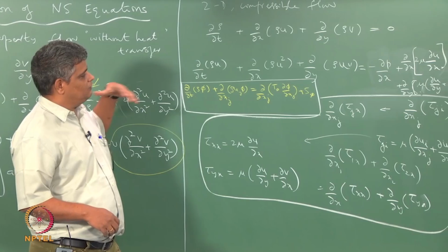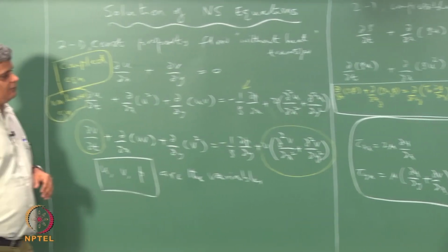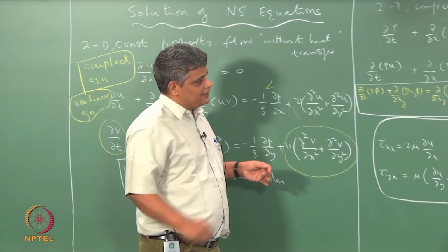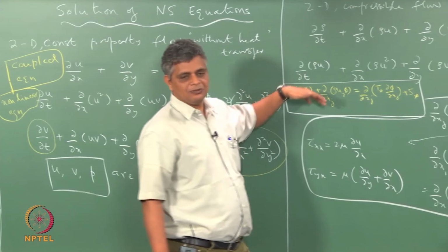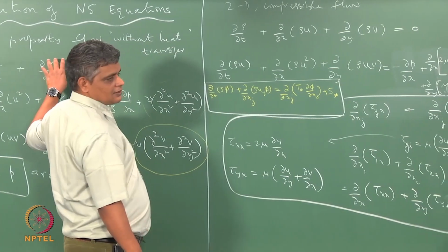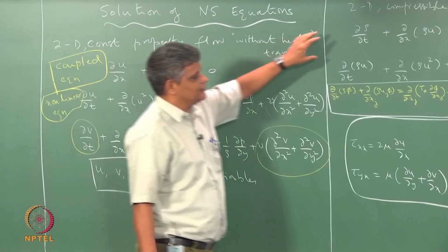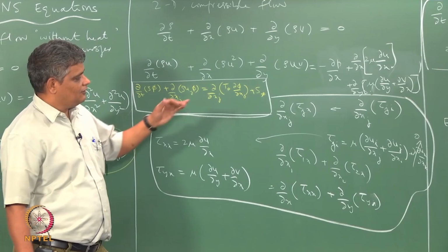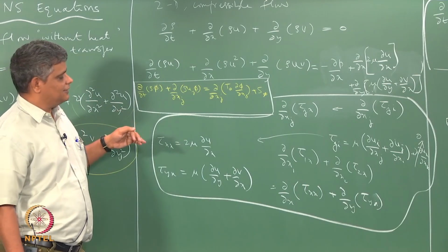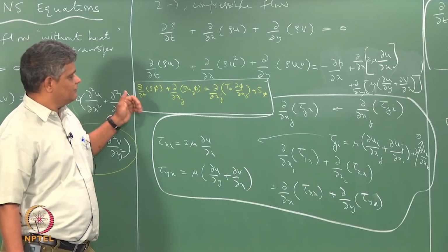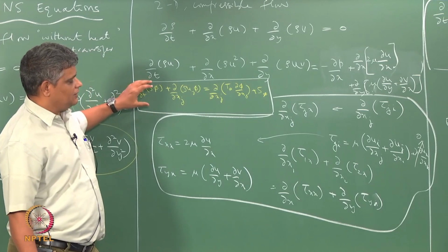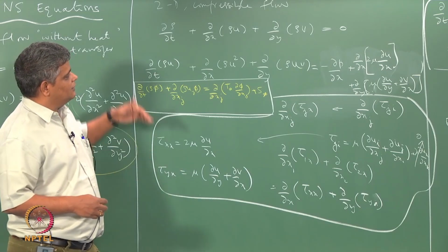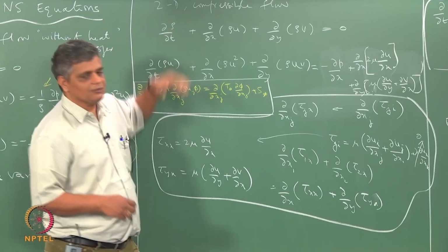We have to think of ways of dealing with the nonlinearity and the coupling. So the strategy is that despite the additional complexity that is there in compressible flow, in the sense that here the equation involves only 2 variables, and here it involves 3 variables, and here we have 3 equations, and here we have 5 equations, there is a natural extension that is possible from the concepts that we have learnt while solving the model equation, and then we will try to create a template. We will examine the templates that have been proposed for the solution of these coupled equations for compressible flow calculation.